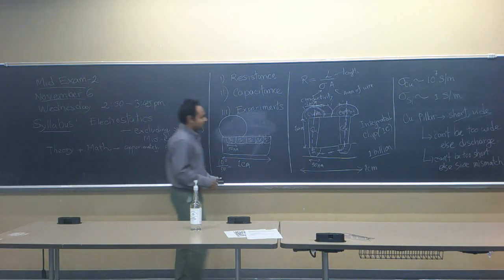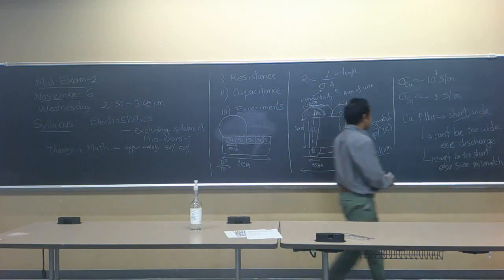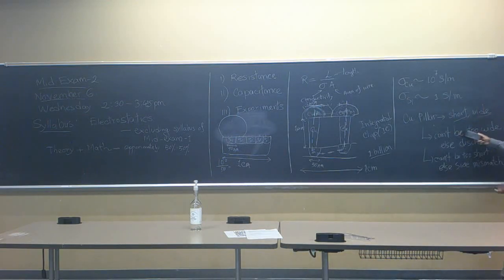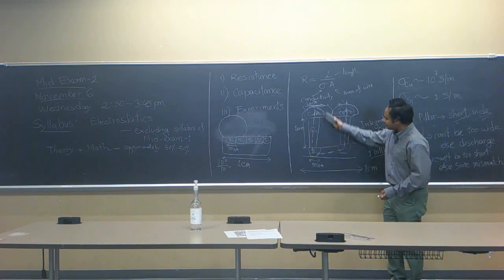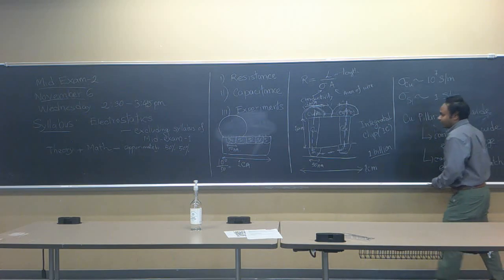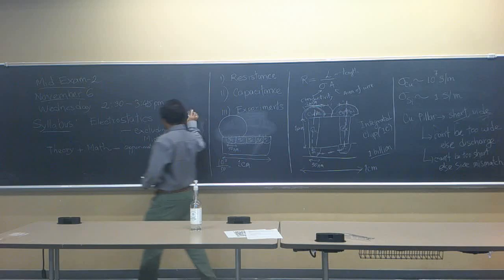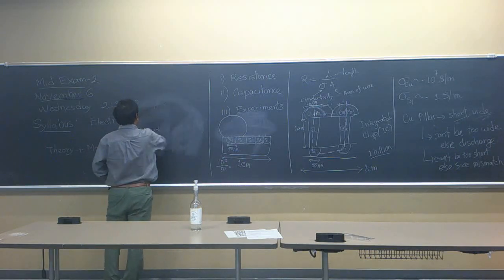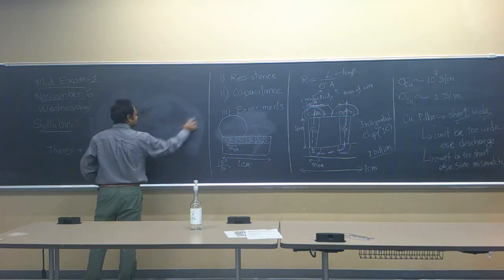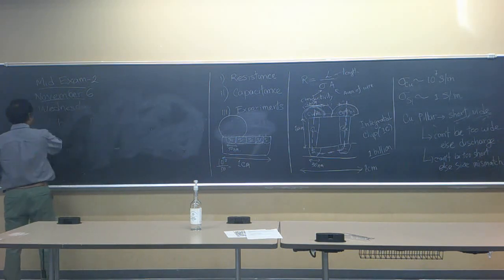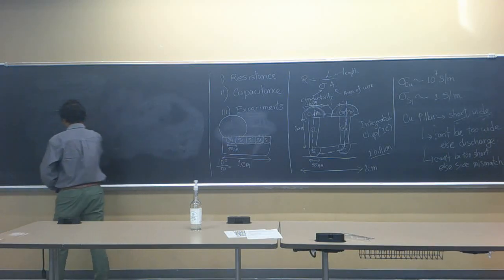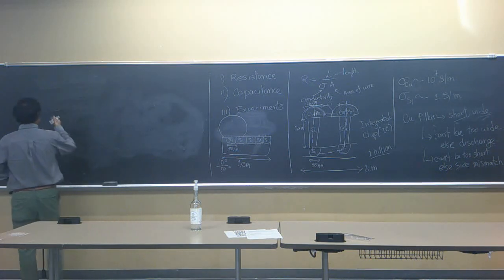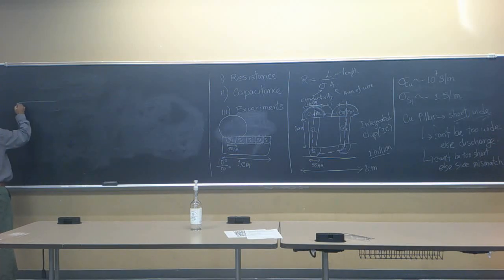Any questions? Alright, so we discussed that the copper pillar has to be short and wide, but it cannot be too wide as they will touch each other. It cannot be too short because then there will be size mismatch. Alright, so how about the following? Let us say we design an IC which looks like this.